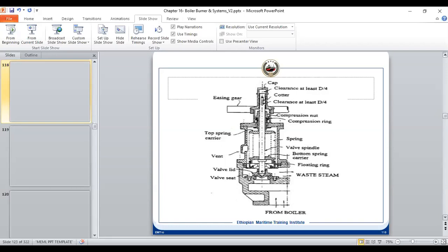Okay, so maybe in a main propulsion boiler, the steam turbine will require more power if the draft is more, and the boiler also needs to produce more steam. So yes, there we could have some implications, but on our kind of ships, like normal tankers and bulk carriers, the boiler is completely independent. If it is a main propulsion boiler, yes, if your draft increases too much, there will be a lot of strain coming on the main engine also, a normal IC engine.